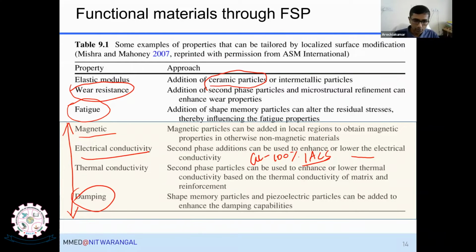As we know, most of us are mechanical engineers, so we know that our lathe bed, or any drilling machine or milling machine, the beds are made of cast iron. Why are we using cast iron? Because cast iron absorbs vibration. And why does cast iron absorb vibration? Because it has graphite in the microstructure.